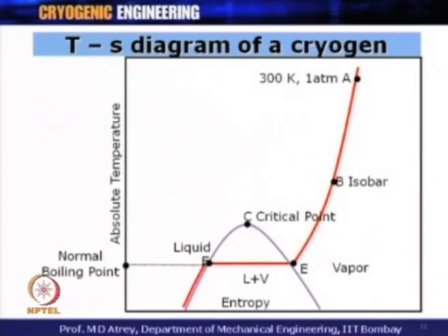It is very significant to understand the critical temperature of any gas. What does it mean? Above the critical temperature, what I have here is a gas. Below the critical temperature, I can get a two phase region, liquid plus vapor, only when my temperature is below the critical temperature. Similarly with pressure lines, if I am coming down over here and I am above the critical pressure, I will never come into the two phase dome. I will bypass this two phase zone and drop on this side. While if my pressure is below the critical pressure, then I will definitely reach inside the dome.